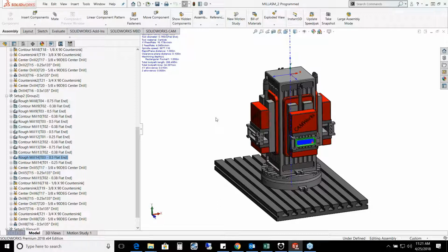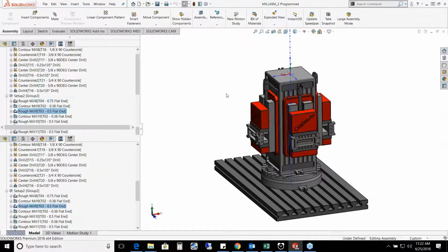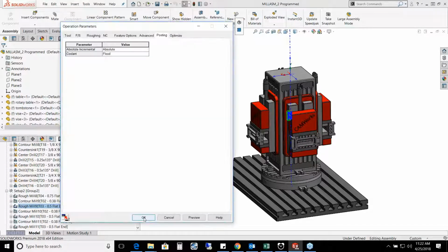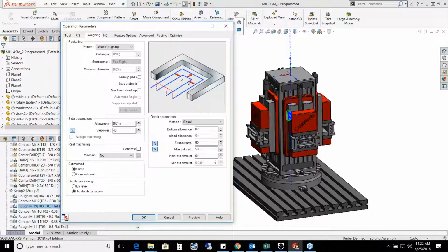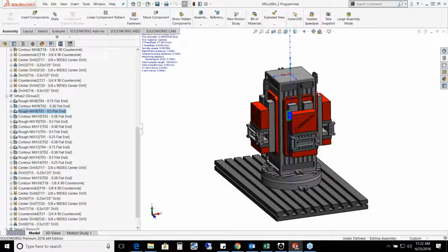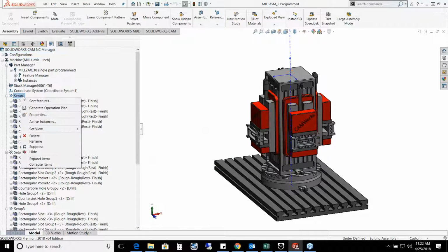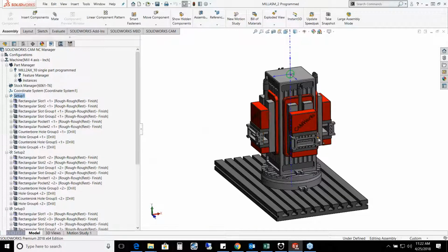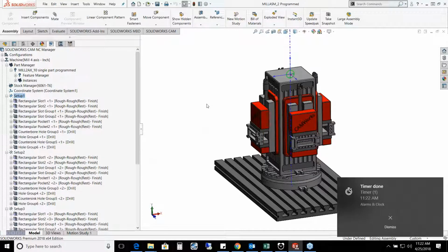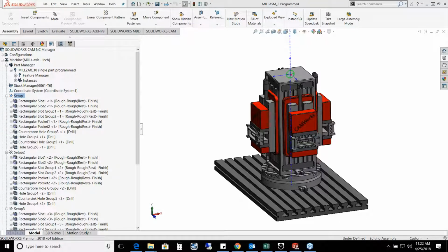The only other thing that I would like to mention is for those people who are doing 3-axis simultaneous toolpath, there is some functionality in SOLIDWORKS CAM for 3-axis machining. It's fairly basic. You can do cusp height control, and you can actually machine a surface. When you create a surface for that part, it's a little different as far as how you would do that. We do cover that in our training classes. And I think that Chris may talk a little bit more about that.